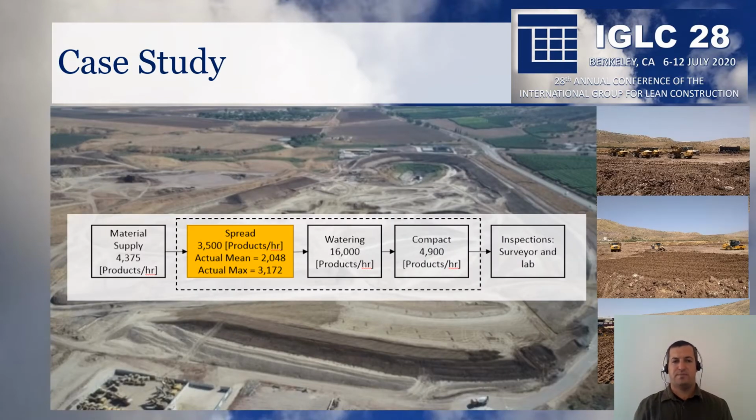The case study is a water reservoir, and we focused on the embankments that were produced from clay that was excavated on site. The operations we focused on were material supply, spreading, watering, and compaction, and of course the quality assurance inspections, by a surveyor and a land laboratory.